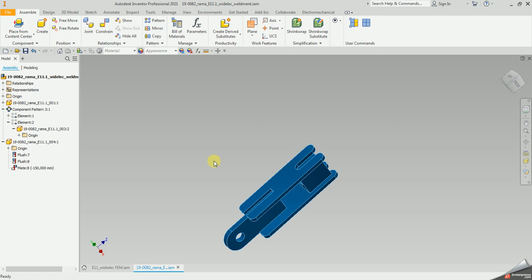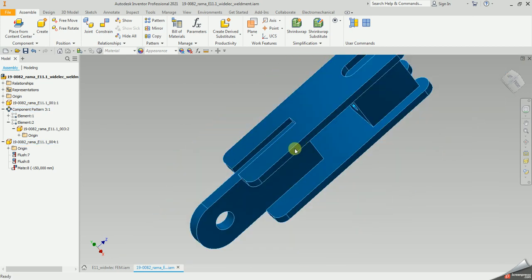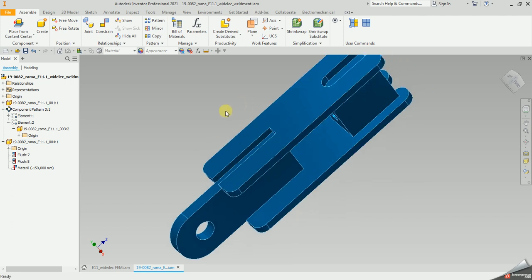So this would be first, if like in this case you make a model of the element including cutoffs or recesses or basically other kinds of preparation of individual parts for welding. In this case there are slots in those plates already designed, to be cut out while making those elements, and these slots are basically here to apply welds at a later stage. So this is one thing. When you have elements that require welds to be structurally consistent in the model,